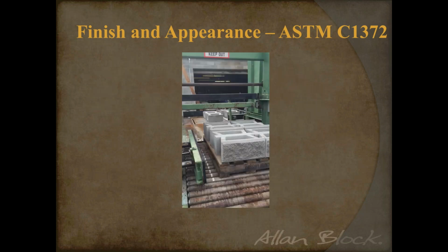So here's another video I want to show you. And this one really goes to how careful our producers handle the block so there are no chips in the block, or very few that happen. Now we are talking concrete. It's the nature of concrete to chip, but you're going to notice an individual walking down here and he's going to very casually roll the block over. So all of these 8 blocks that are coming are all upside down. So the lip is down. You'll notice that the pallet here has the first course of block, and all of these blocks are placed with the notch up, or the right side up. So let's take a look at the video.